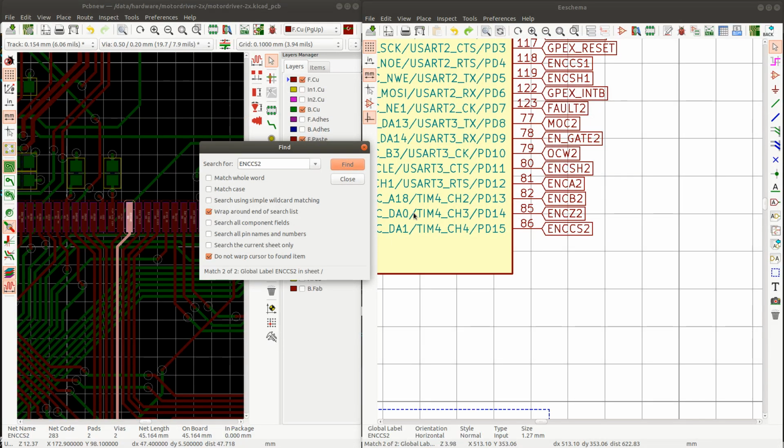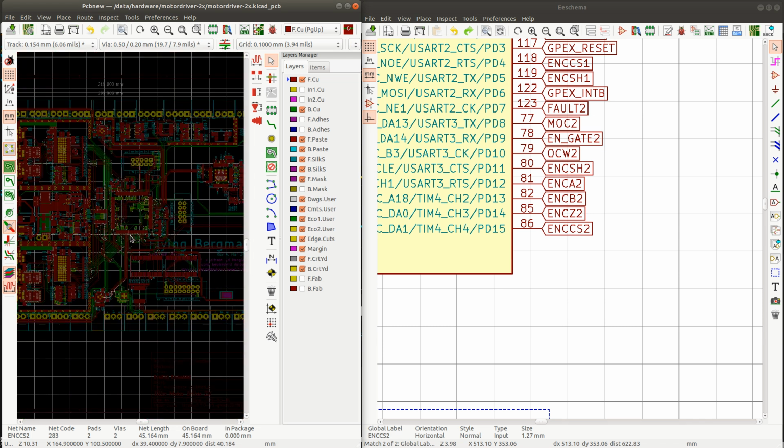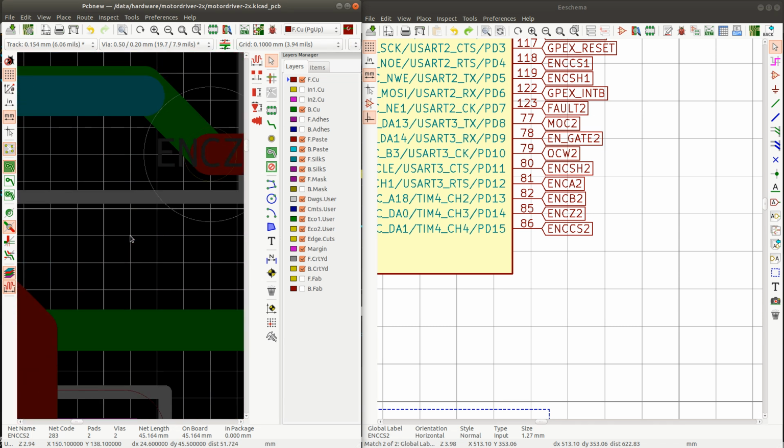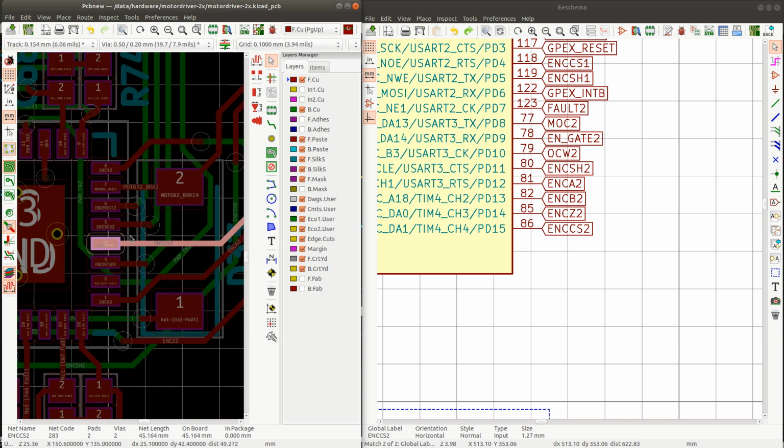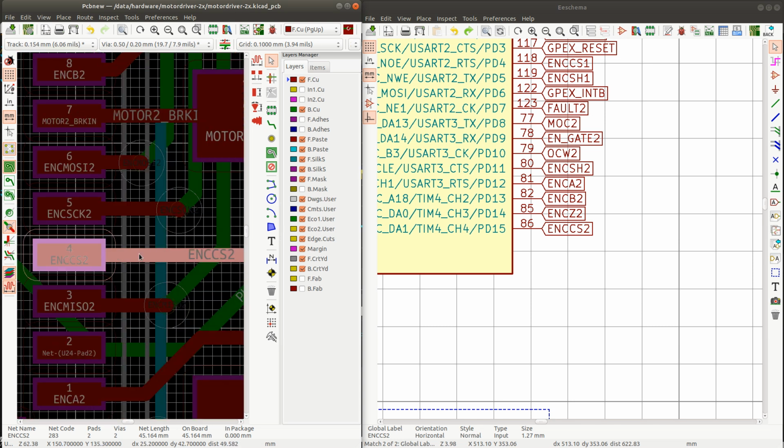So this was on, I think, let's see, I'm going to check what pin it is. This was master in, slave out. So the chip was actually responding. But something else is not right. Maybe I misconfigured the... I don't know. It should be fine. It's exactly the same pins as the other chip. So the only thing that was not the same was the CS pin. But why is it not working?